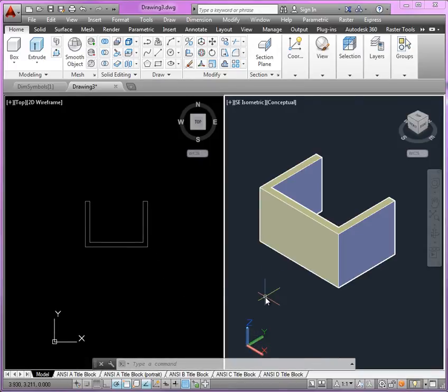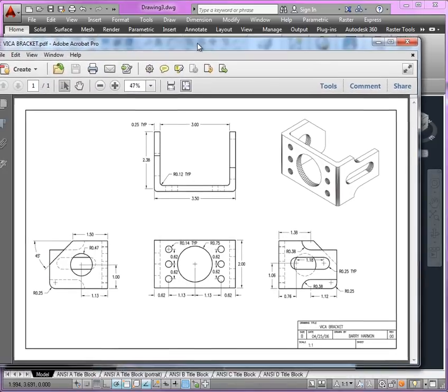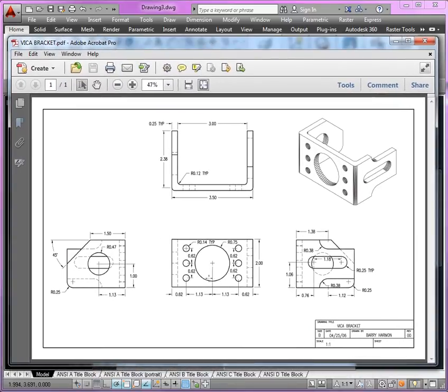And so as we proceed now, what I would tell you is take a look at each of the faces of your model. If I show you here a sample, you can see we have features in the front face, features on the right and on the left face. Now what we could do here is use the 3-point UCS to create a new UCS on each face. Okay, that'll help us to use our traditional drafting tools, or 2D drafting tools, and our traditional approach to lay out the geometry accurately.